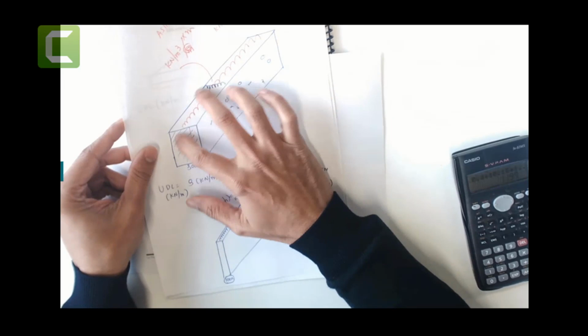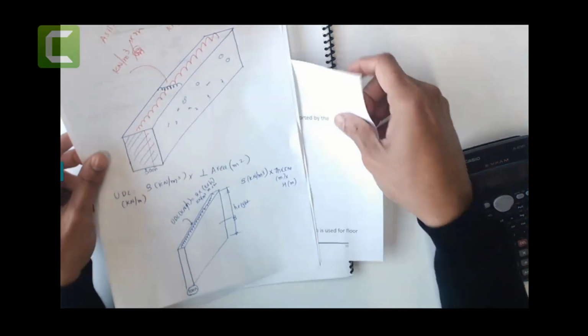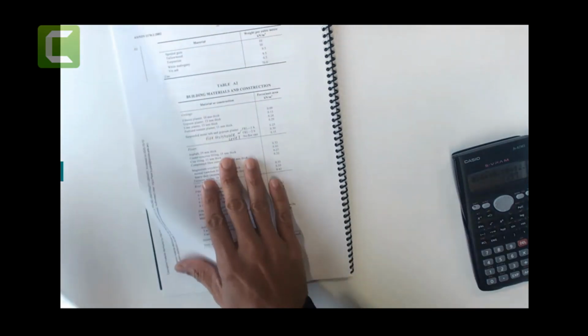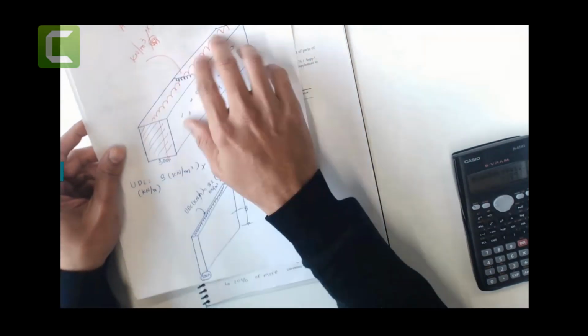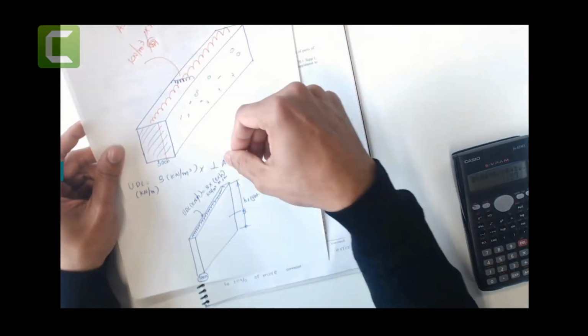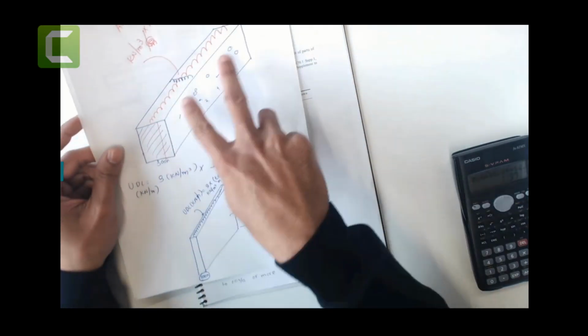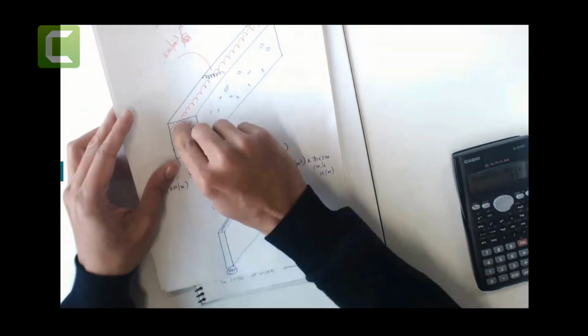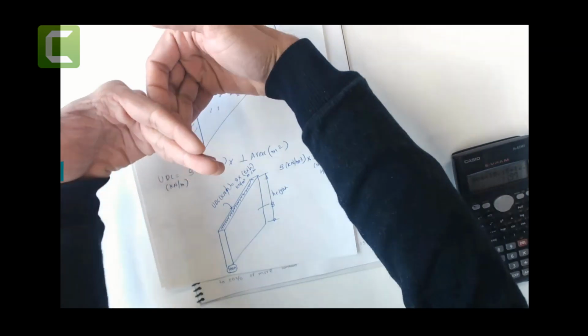If you come across density and you want to convert to the UDL load, you multiply by perpendicular area. How come you're going to come across density? Because this table A1 has noted this kilonewton per meter square. That's it. If you have density, convert into UDL load, multiply by meter square, there are a couple of meters square, just check the perpendicular. If you are considering UDL load in this fashion, so this is the one and this is perpendicular.